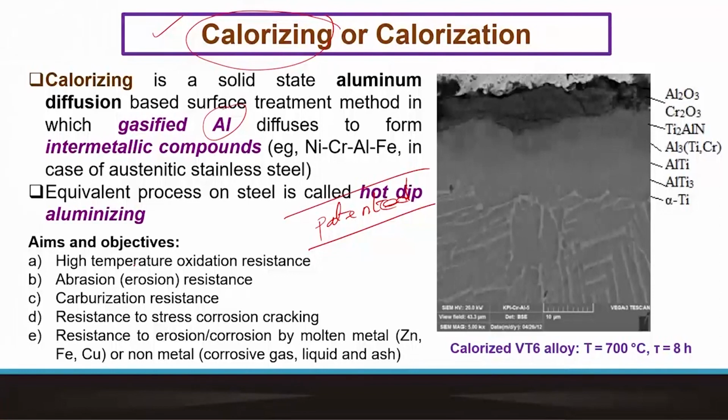It was patented initially in the USA and was highly utilized, and even today it's one of the most effective methods for iron, cobalt, nickel base alloys, particularly the superalloys. The turbine blades, the vanes and discs and so on are routinely provided with these kinds of coatings.